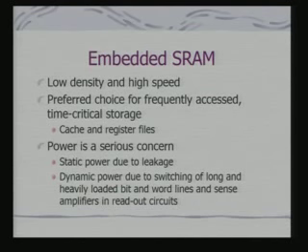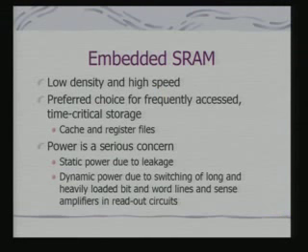But wherever you are using static RAM, power is always a serious concern, because in an embedded system we would like to minimize usage of power. In a static RAM, what are the sources of power loss or power consumption? One is static power loss due to leakage, because you have seen the transistors on the path. So, there will be a leakage current even when you are not actually accessing that memory, because that memory is in an active state, it is storing the data that you have stored. So, there would be a leakage current, and that is what we call a static power loss.